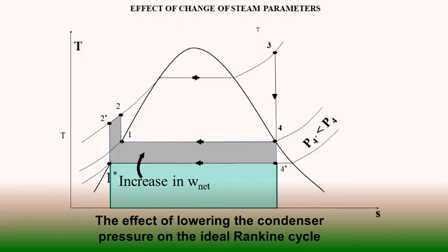That means if we want to reduce the condenser pressure, naturally we have to give more circulating water flow across the condenser, which will require more pumping energy. So at a particular level, reducing the condenser pressure further is not economical in totality with respect to CW pumping energy consumption.